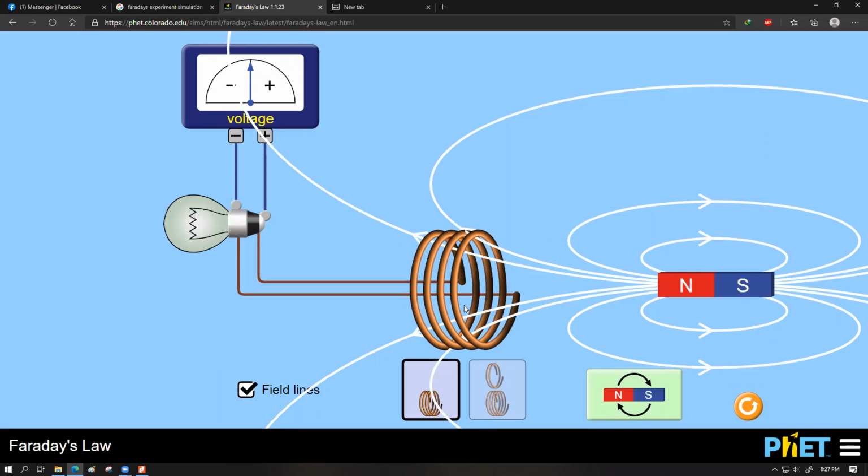Always. This is where the idea becomes very interesting: whenever we do some movement, displacement against a force, we have to do some work. What Lenz's law tells us is that it is the work that we are doing against this force that is being created as electrical energy in the coil. So every bit of work that we do against this resistive force is going to be converted into electrical energy in the coil. So if we want to increase the amount of electrical energy output, we have to increase this amount of work done.